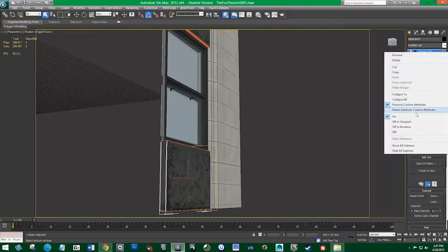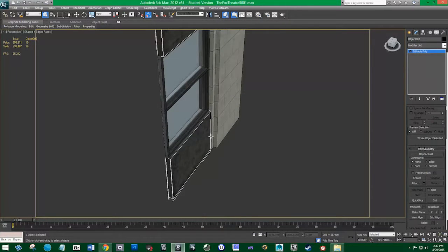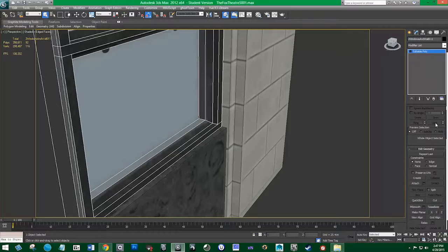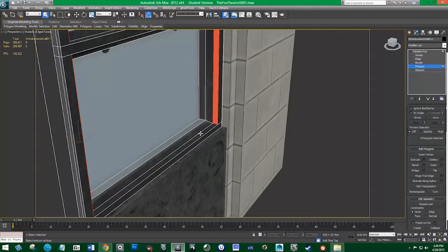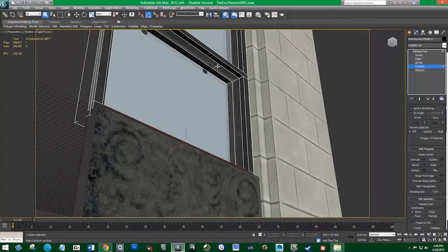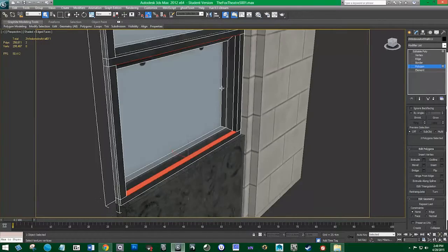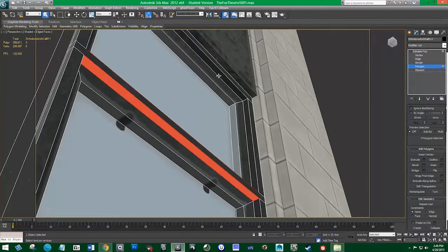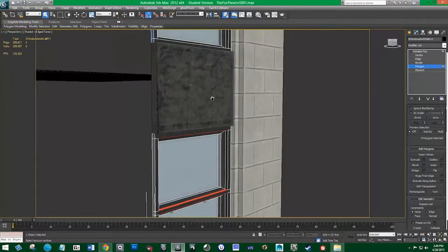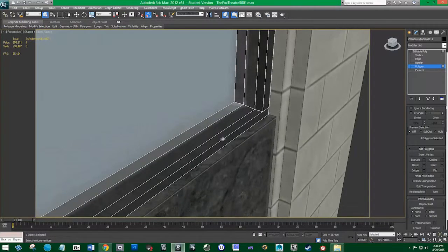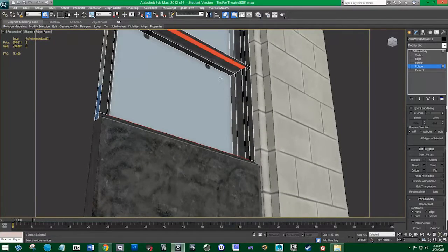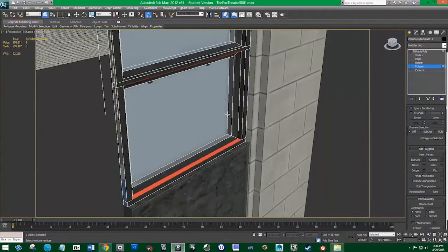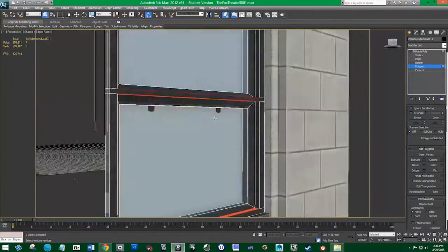It's just got the manipulator to show you where you selected. Click on that. And then we're going to do this again and go to the UVW Map first. And right now we're on the x-axis, so we don't want that, we want the y, and then hit fit, and that'll fit the y to this plane.